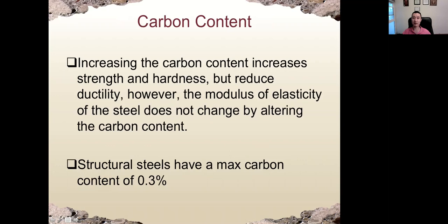So we increase the carbon content, we increase the amount of cementite. Okay, so strength will be higher, it will also be harder, okay, but that will reduce ductility. But the modulus of elasticity will not change as much by increasing or reducing the carbon content.